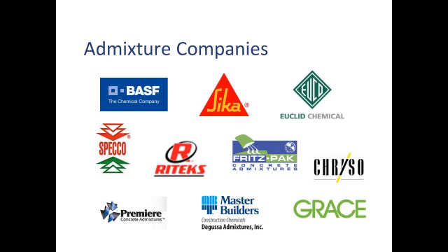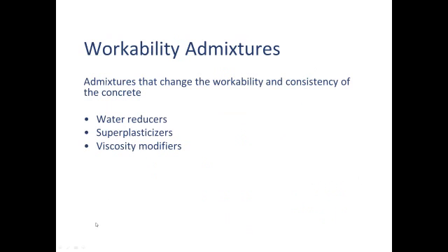Now, I'm going to be mentioning specific products that I have used, that I trust, that many people trust my recommendations with regards to concrete countertops. So don't feel that you have to buy what I say. But given that, if you do use what I say, you are going to be getting the kind of results I expect you to be getting. And that goes a long way to having confidence in your product. So let's first talk about admixtures that change and modify the workability of the concrete, how stiff or how runny, how fluid it is. And these include water reducers, and a subset of water reducers are plasticizers, and viscosity modifiers. And I think these are some of the most important admixtures that you're going to want to have at your disposal.